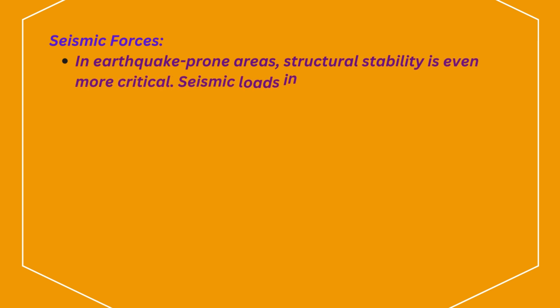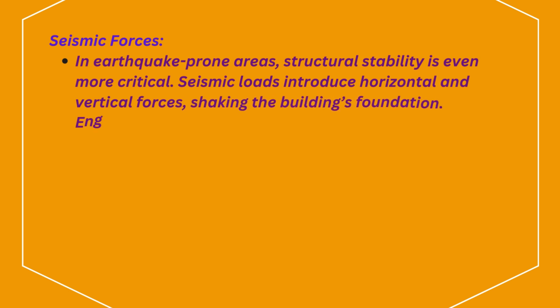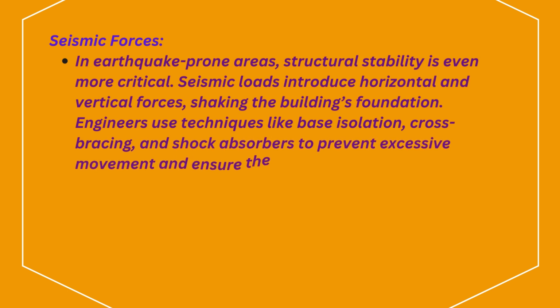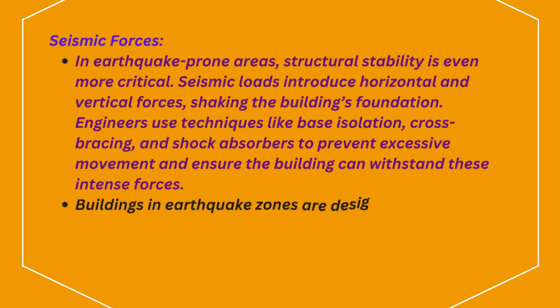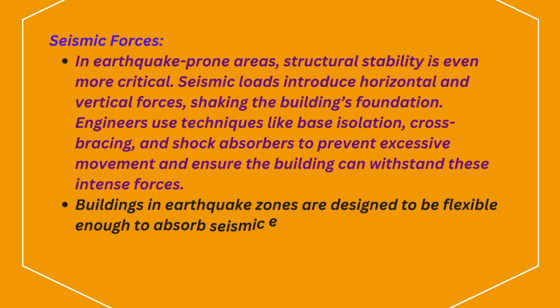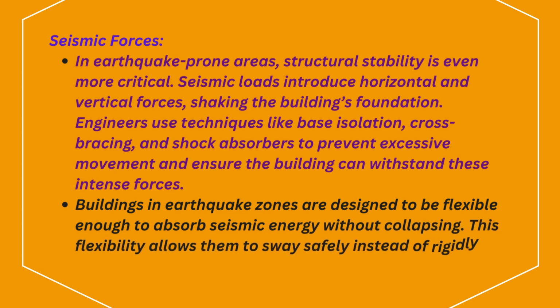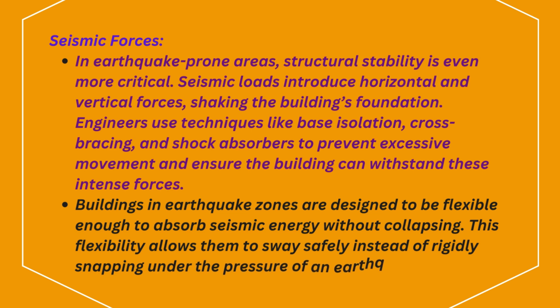Seismic forces. In earthquake-prone areas, structural stability is even more critical. Seismic loads introduce horizontal and vertical forces, shaking the building's foundation. Engineers use techniques like base isolation, cross-bracing, and shock absorbers to prevent excessive movement and ensure the building can withstand these intense forces. Buildings in earthquake zones are designed to be flexible enough to absorb seismic energy without collapsing. This flexibility allows them to sway safely instead of rigidly snapping under the pressure of an earthquake.